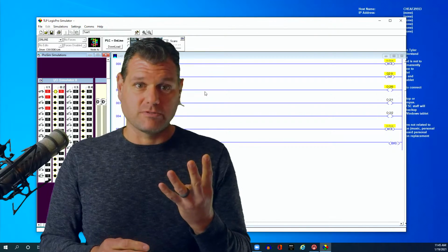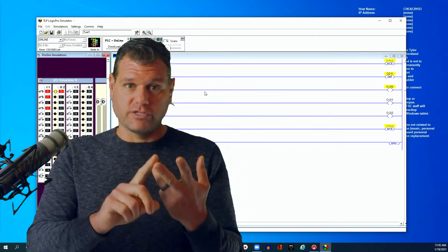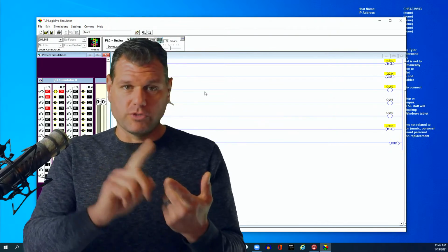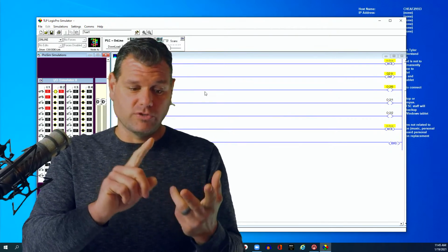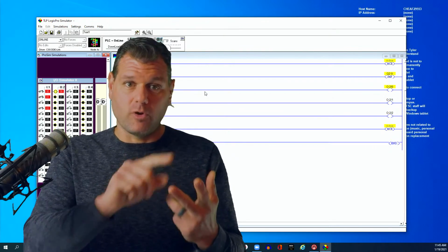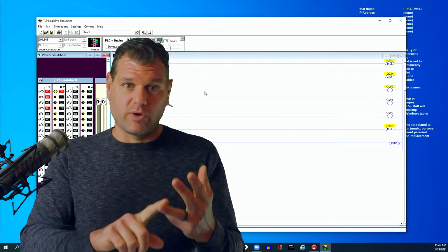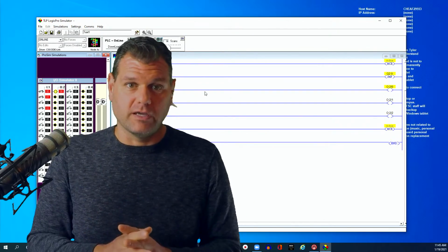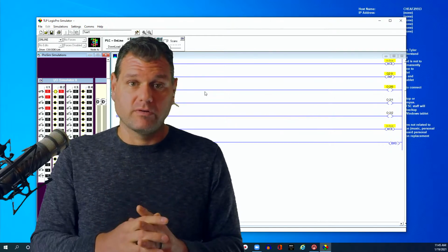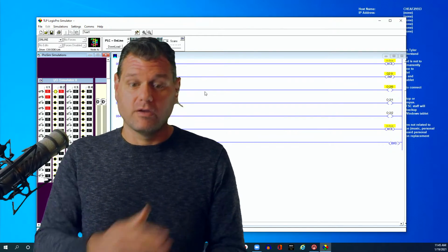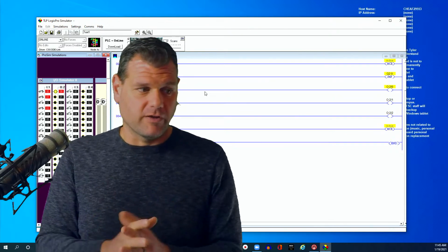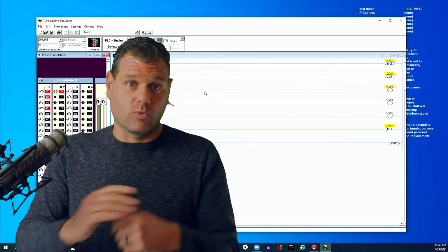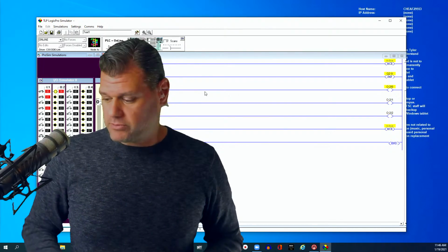Because remember, it has those 4 steps. You scan your inputs first, you read your logic, it updates the outputs, and then it does all its housekeeping stuff, its networking stuff. So when you scanned it, that's your first scan, and then when you do the logic, it says, okay, I'm going to skip over these sets of rungs, and then when I update, nothing's changed because it told me to skip over. It didn't care, and then it's going to go ahead and leave it on, and then the next time around, if the jump is not there, it will scan it and turn it back off. But just be very careful. So a jump will leave it whatever state it was in, whereas a MCR will completely turn everything off. So that's the big difference in those two.